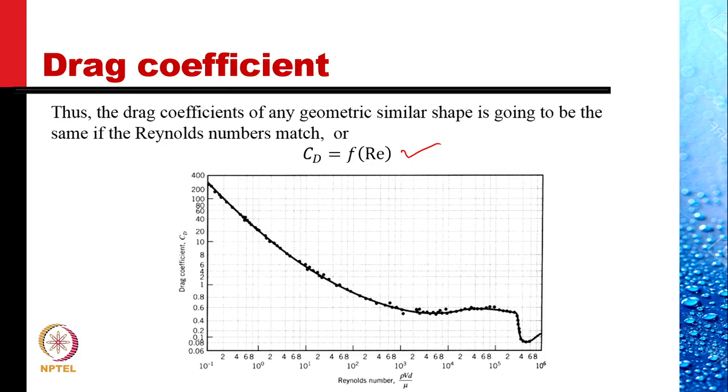An interesting thing to notice, however, is that over a large range of Reynolds number, from about 10 to the power 3 to 2 into 10 to the power 5, the drag coefficient is effectively independent of Reynolds number. This fact